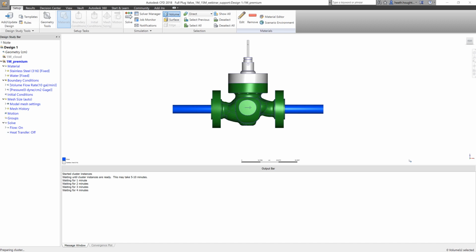So what I've been doing is solving everything to convergence, and like in this model, I stayed 1,000 iterations. I know it'll be done by 1,000 iterations. It'll be somewhere probably between 200 and 500 iterations typically, and that's what I've seen for these models. So I just specify 1,000 and run it, and then I get more and more experience. I might lower the iteration count, but I don't do an exorbitant amount of iteration requests. I don't say 10,000, and I don't say just 100. I just state something that I'm pretty sure it'll be converged by. That's my rule of thumb. That's the way I roll them.